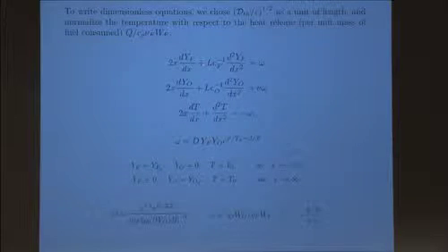The other parameters are clear, known, the same notation as before: the Lewis number of the fuel, the Lewis number of the oxidizer, and nu is the stoichiometric ratio of oxidizer to fuel, mass-based. Beta is the activation energy parameter, and here I scaled the temperature not with respect to the unburned cold temperature, but rather essentially with the heat release.